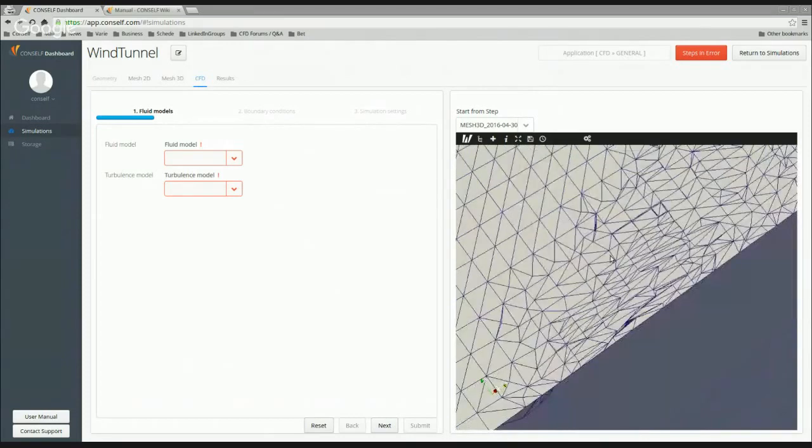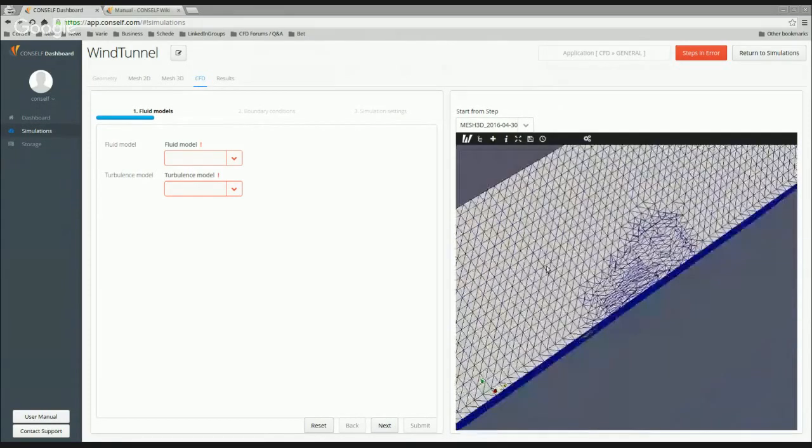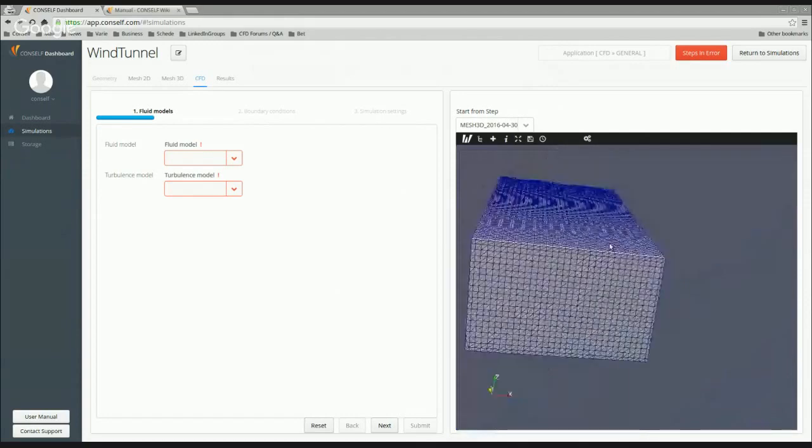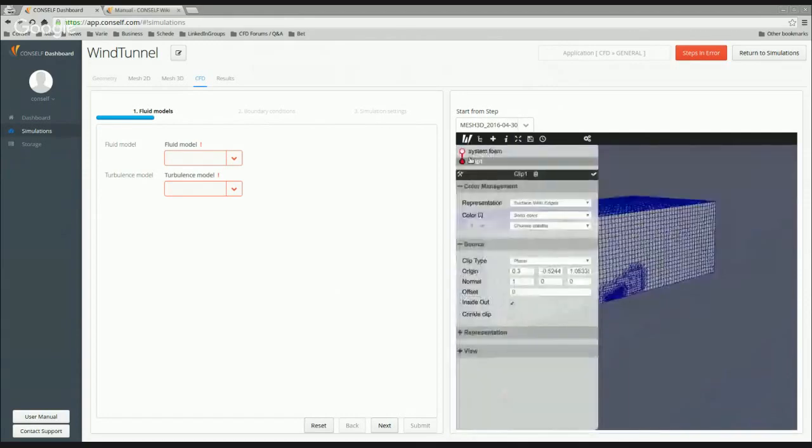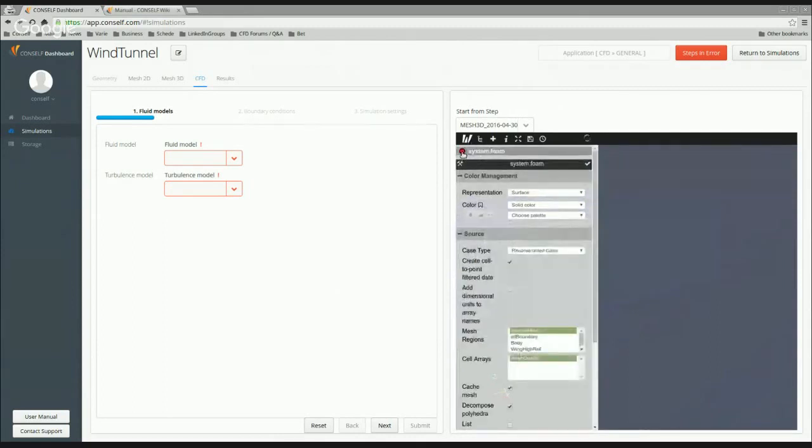So finally, I want to show you how to find out if the quality of your mesh is good enough. If you just delete the clip, and come back to your file, you can color it by mesh quality. Choosing it, you will see that the majority of your mesh will be blue. This means that the majority of your mesh is okay.